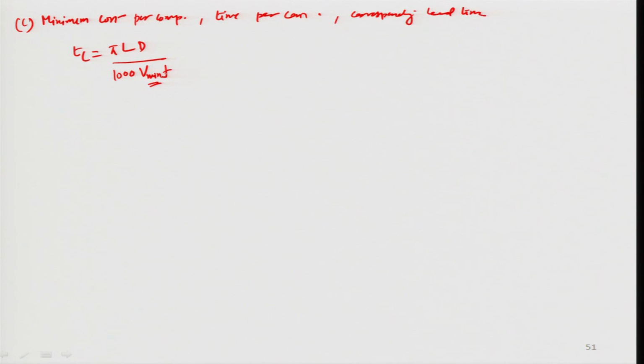82.337 meters per minute, and we can write this here as 3.14, the value of pi, times the total length of machining, which is about 300 millimeters, 30 centimeters long. That is how the question recorded. In terms of the length of the workpiece, the diameter was 6 centimeters.